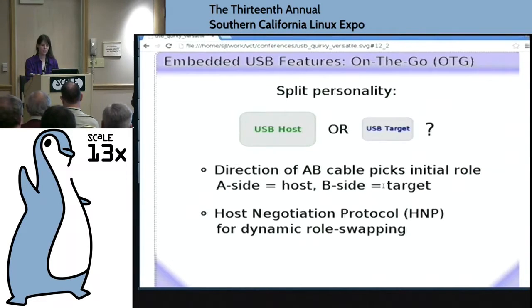You'll find test pages online that tell you how to do this role swapping. It seems to be kind of board specific though. It's like, well, if you go poke this over in the SysFS area, then you can trigger a role swap. I haven't found any standard ways to do it yet.